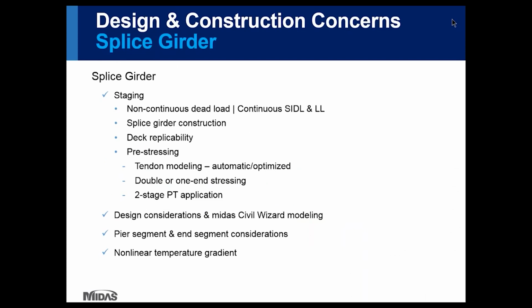So some of the design and construction concerns regarding the splice girder application, in terms of staging, running the dead load non-continuous and superimposed dead load and live load continuous, spliced girder construction, and deck replacement, pre-stressing for tandem modeling. As mentioned before, you can do it automatically or you can optimize it.